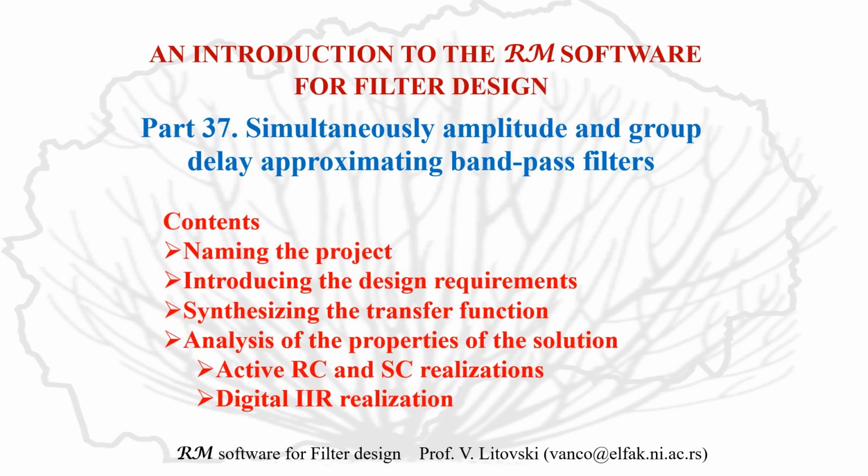Then we will go for the synthesis of the transfer function and analysis of the obtained results, and then we will go to system realization, which in this case is limited to active RC, active SC, and digital infinite impulse response realization, meaning that the RM software is not offering LC realization of this kind of filters.